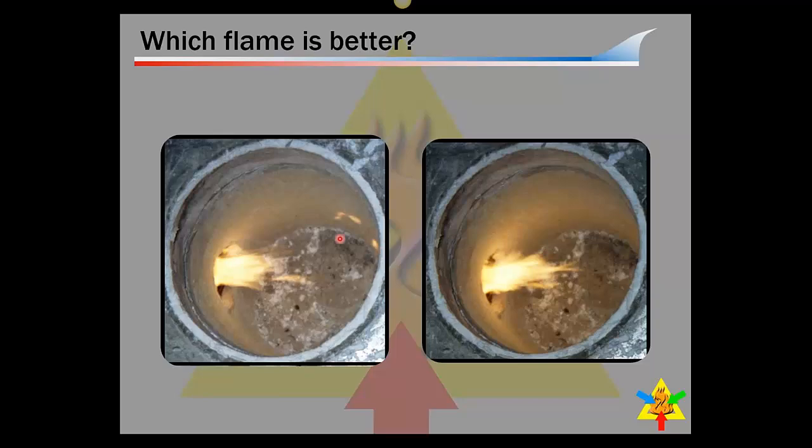There are some subtle clues that if you know what you're looking at, yeah, you can kind of get a good idea. But even looking at this, there isn't a person alive who can tell you which one of these flames is producing the most amount of carbon monoxide, which at the end of the day is one of the key things we're looking at. The only way you can make that determination is through testing. And that's why we do combustion analysis and testing. Because you can't look at a flame and say, oh yeah, that flame's good, everything's okay. We have to test, okay?